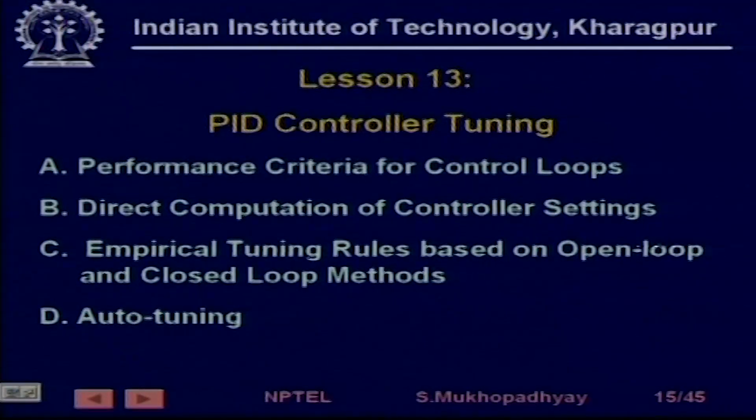Auto tuning is where the controller itself examines the input output signal and from there decides the best controller parameters for this process, and then downloads them into the controller. Basically it sets the PID controller parameters to those values, without human intervention, and we described the method using relay control systems.